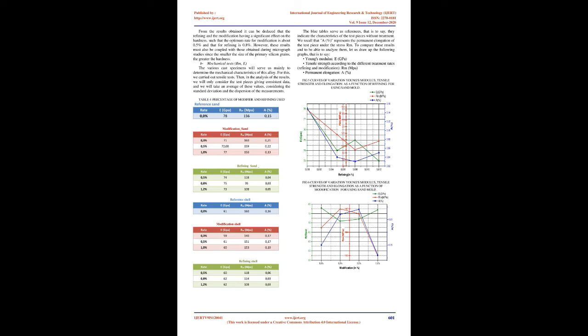As these hardness measurements were performed on the aluminum alloy Al-Si17, we used the Rockwell ball hardness for our tests. The values given below are average values calculated from the 3 most significant values out of 5 measurements for each sample. The table below represents the results obtained.